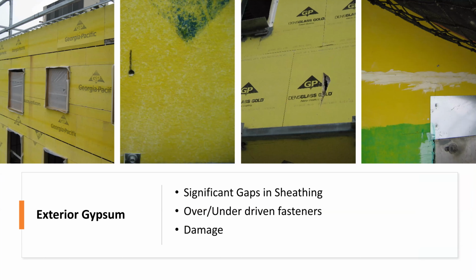Now, if you have things such as overdriven fasteners, those will tend to be more of an issue for fluid-applied membranes, maybe not as much of an issue for something like a self-adhered, unless there's like a million of these screw holes in there. This tends to be more of an issue with the fluid applied. And then you can see if we do have some damage, obviously we can't just put a piece of self-adhered membrane over top of it. Those only have the ability to span a certain gap.